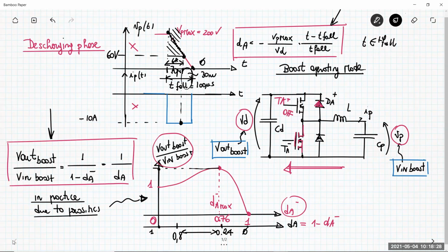Summarizing all the discussion, it can be useful to recover the energy. You spend energy for elongating your piezo injectors, making the injectors open to inject the fuel into the combustion chamber. Then in another phase, you have to compress your device in order to close your injectors. In this phase, you are recovering energy, which is good to recover the energy previously spent.